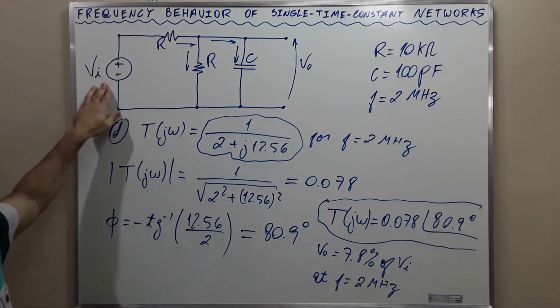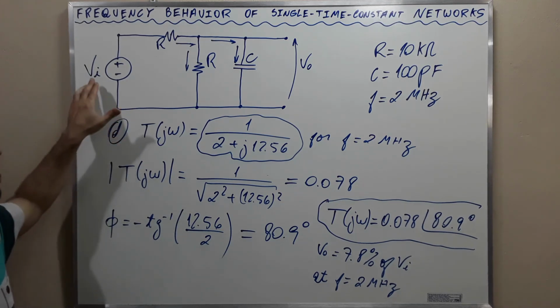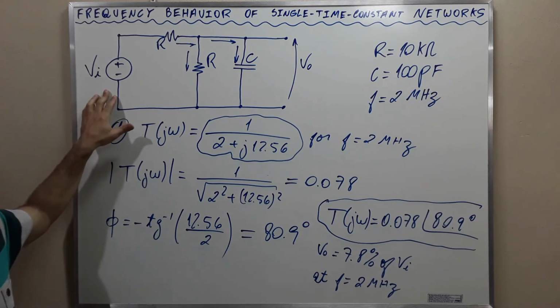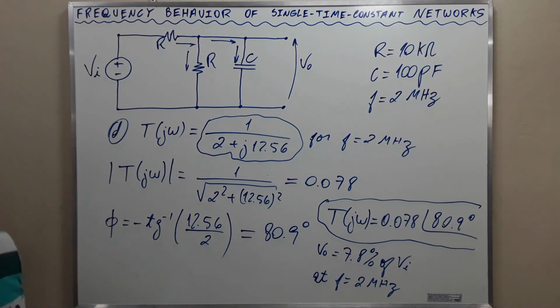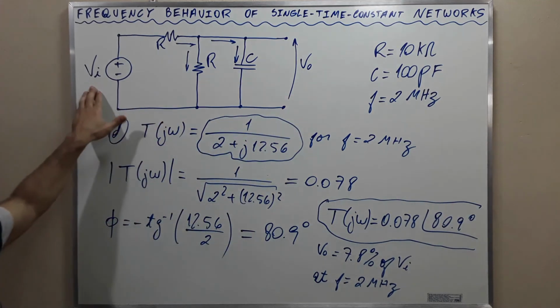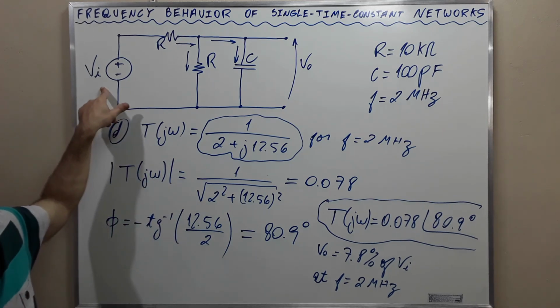We establish one magnitude and don't vary the magnitude of the input, and we keep increasing the frequency of the signal until we have a map of the output with respect to the input, showing how the circuit behaves as we vary the frequency of the input signal.